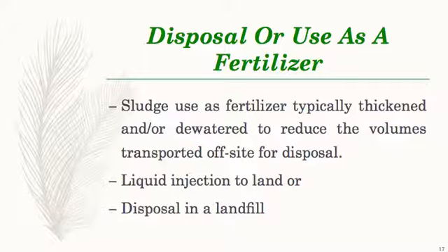The processes for reducing water content include lagooning in the drying bed to produce a cake that can be applied to the land or incinerated, pressing where sludge is mechanically filtered, often through cloth screens, to produce a firm cake, and centrifugation where the sludge is thickened by centrifugally separating the solid and the liquid medium.